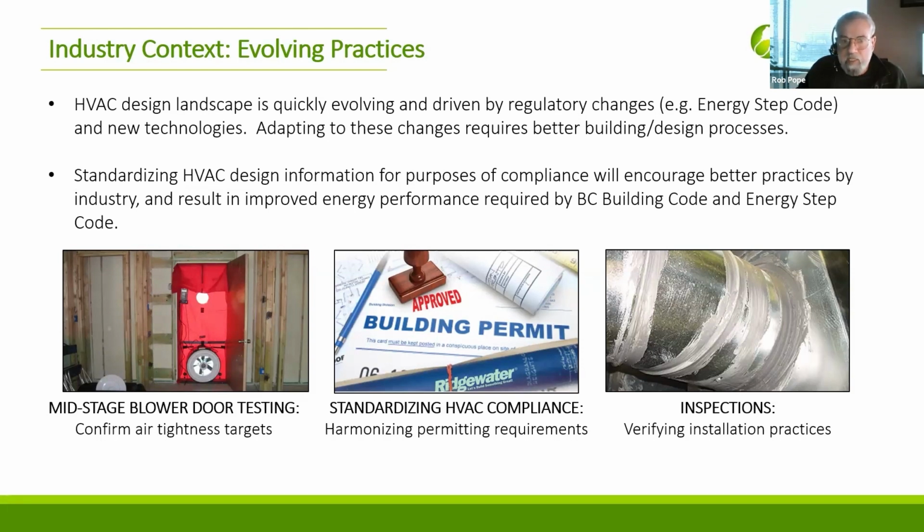If you fail at that stage, at the final stage, then it's a catastrophe, right? So do it before cover up, so that if there's any issues, you can deal with them then. You can fix anything at that point. So mid-stage blower door testing is evolving as a standard of practice, and it's also going to be evolving, as it is in some jurisdictions, as a requirement.